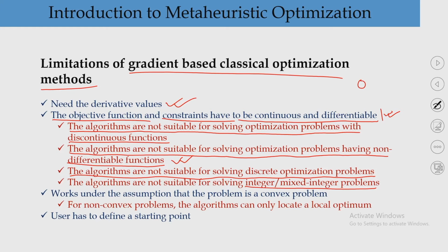Suppose you get 8.5, or suppose your optimal solution is an 8.5 mm bar that you need to use in that beam or column. Now, 8.5 is not available in the market, because either you will get 8 mm, or 10 mm, or 12 mm, then 16 mm, then 20 mm, like that. So 8.5 is not available.